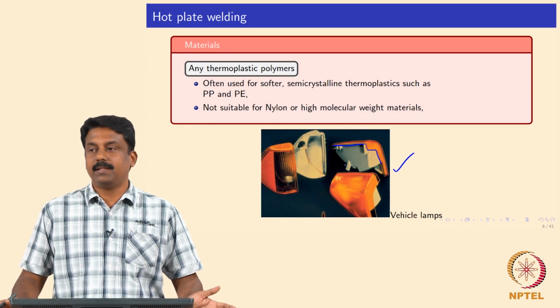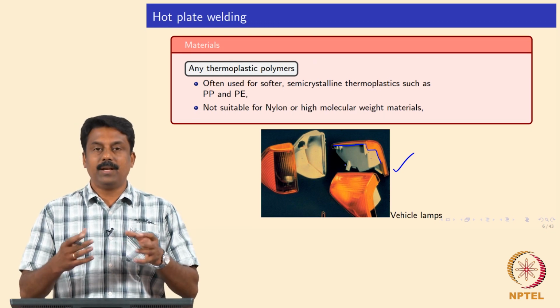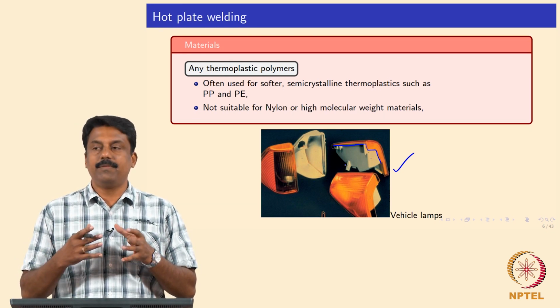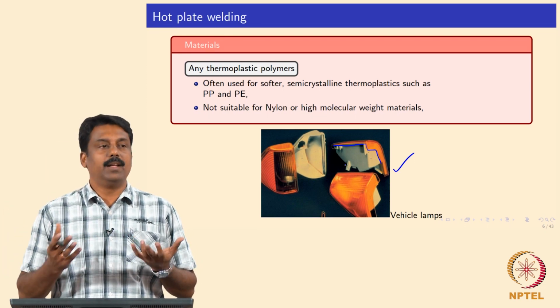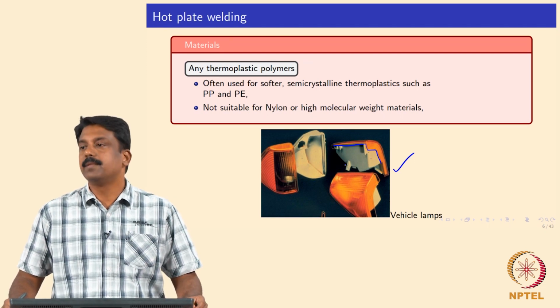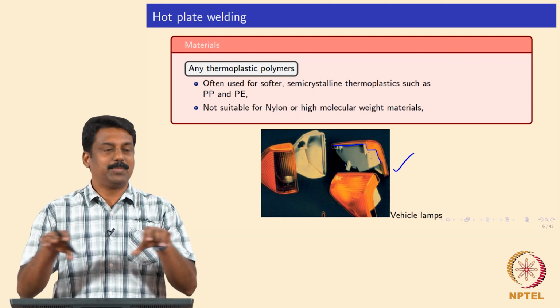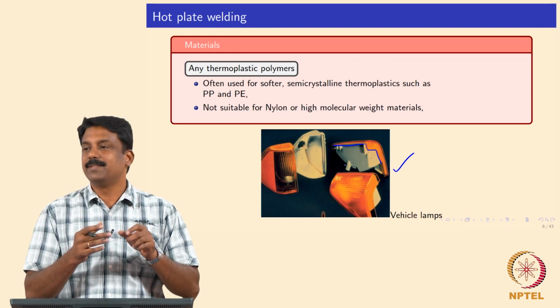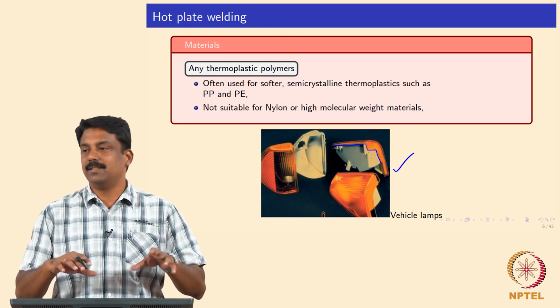Yeah, so semi-crystalline thermoplastics become extremely softened. The component itself should have some strength, otherwise how do you do an upsetting? For example, a flexible rubber polymer: you can't use that, such as collapsible rubber tubes. You need to have some upsetting force, otherwise how do you apply it? If you melt it, it doesn't have any mechanical strength at all.